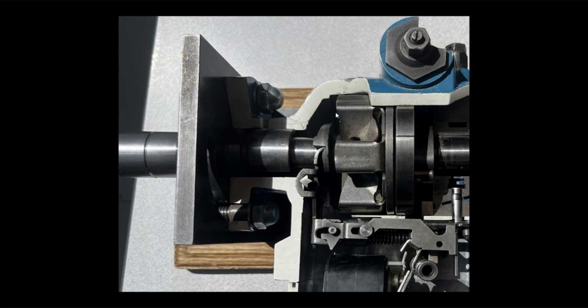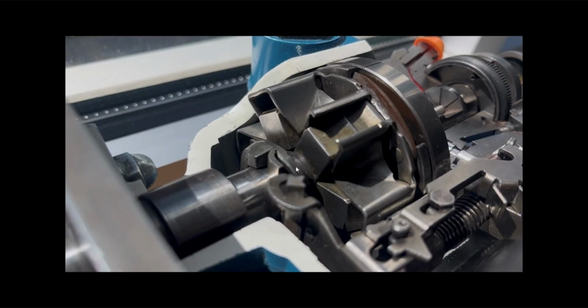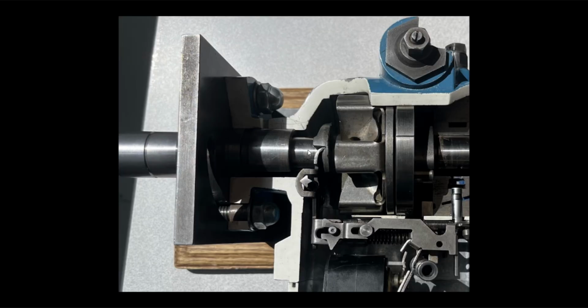On our opposed plunger pump, the governor is located right here, on the opposite side of the pump's inlet. As we can see, the governor is mechanically linked to the metering valve. This specific governor consists of multiple flyweights. As the engine speed increases, these flyweights naturally want to move out due to the centrifugal force imposed. As the flyweights move out, they pivot and push the thrust sleeve against a spring force. This thrust sleeve is linked to the metering valve, which then actuates the inlet metering valve, adjusting the volume of fuel being supplied.